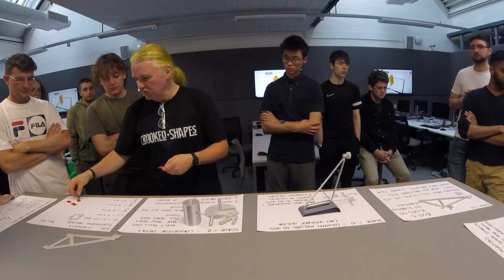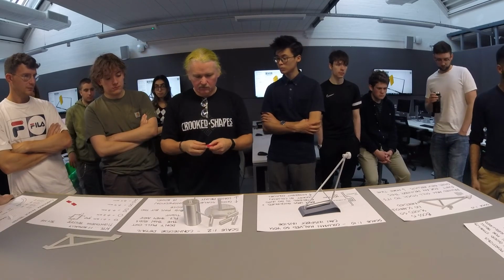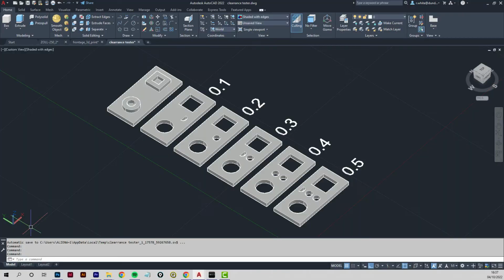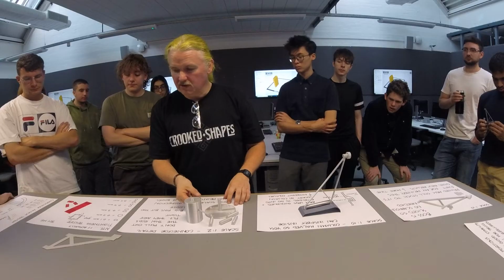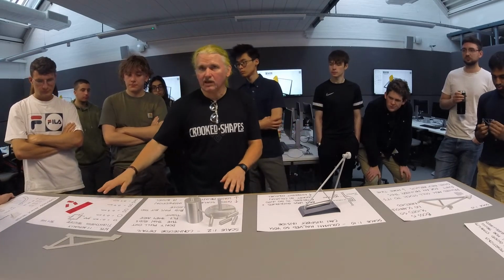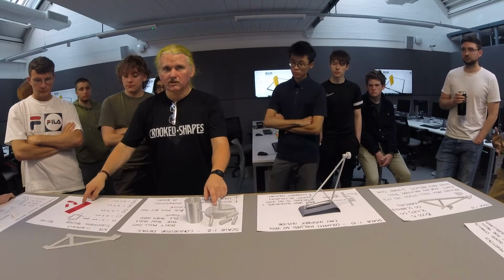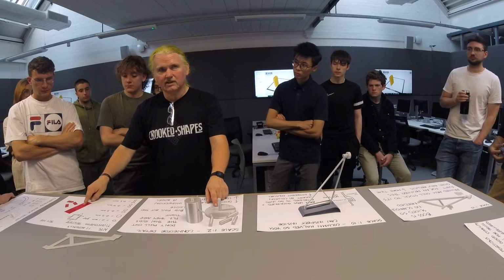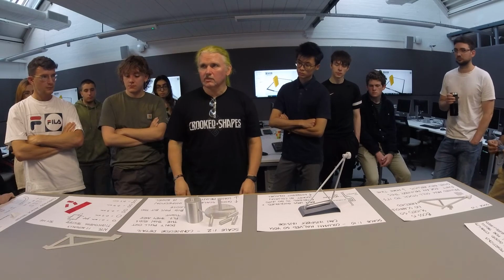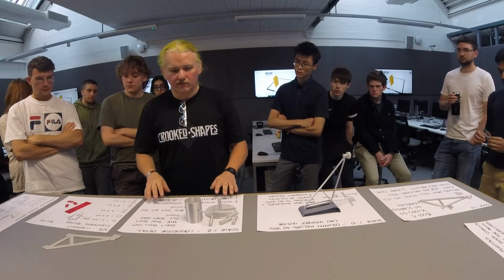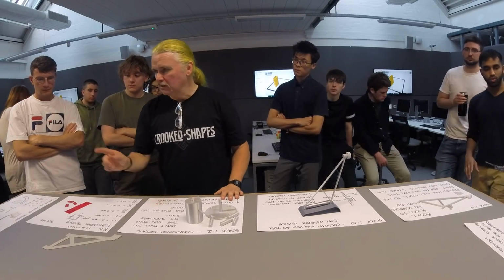But then I've just got different sizes. So move up one, and then you can see it's kind of usable. You often see people get their own little testers for different materials, because a different PLA, even a different colour, can behave differently. That one's not going to work the same as that. That one might be tighter than that one, given the same dimensions. It can be quite fickle. You have to do little tests all the time. So let's have a look at these last bits here.